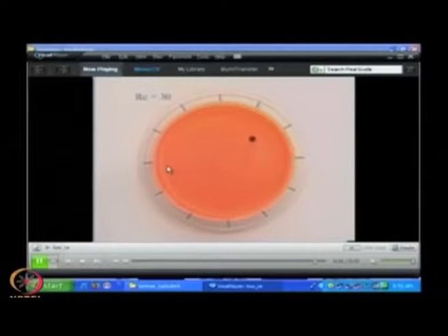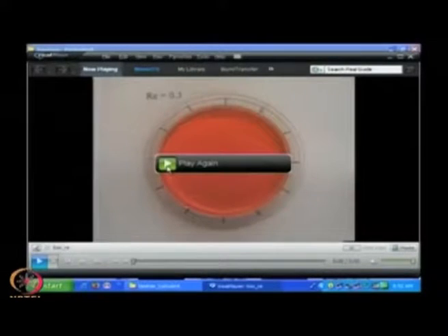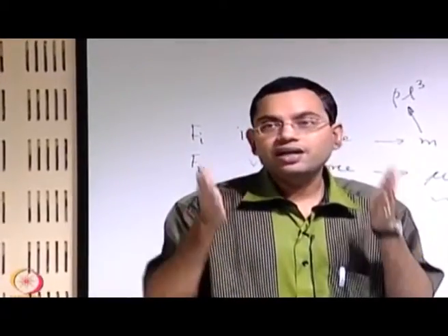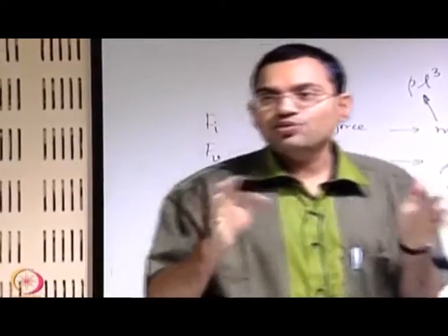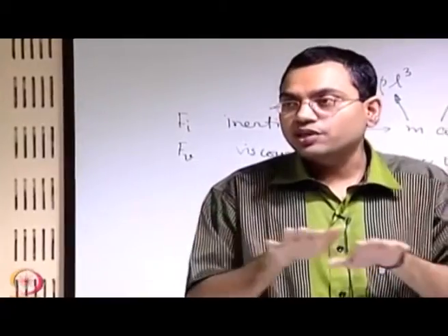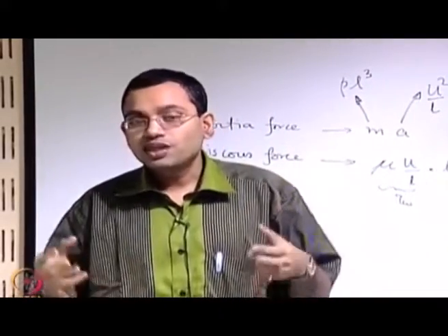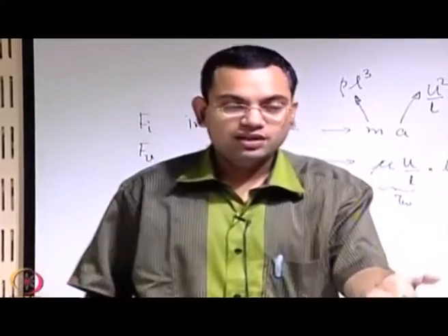One of the reasons is the roughness of the wall of the tube or the pipe, which perturbs the flow. Also the initial conditions, the entry conditions, might fluctuate and might not have well determined, repeatable values. So you will always have perturbations with respect to some average or expected condition. These perturbations are always there in these experiments.